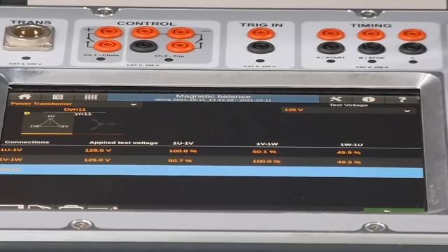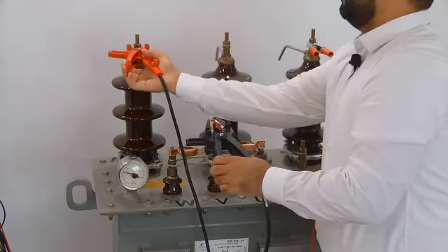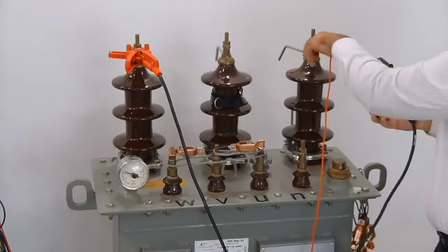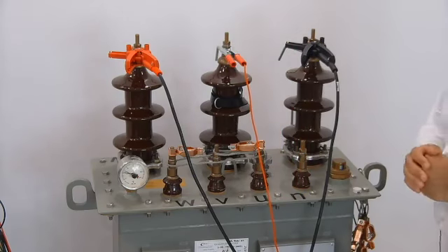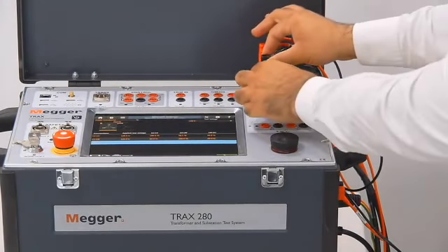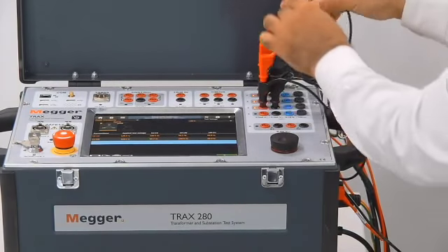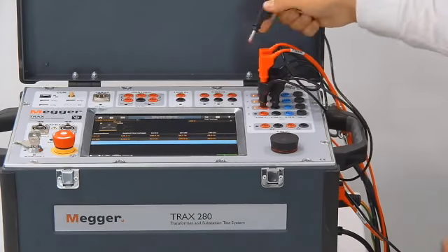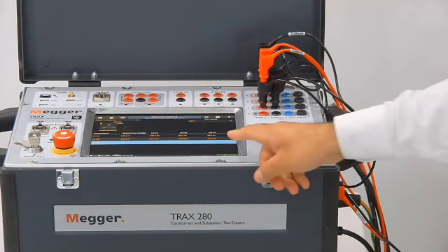We'll now start switching on the power transformer for the last phase. So I will go between W and U, and the remaining will be only measuring the voltage. On my tracks again, I will be making another loop. I will take this and make it one step down. So now I have the full connection. I will click play on my track screen.